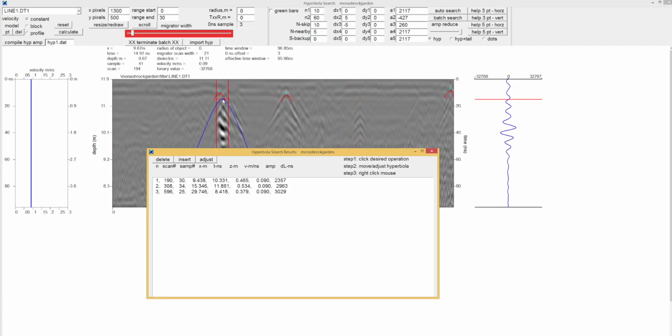And sometimes, as you can see, it gets it completely wrong. This is why this system is really only designed for use on concrete, where you're looking for reinforcing bars, or rebar, where 99% of the time in concrete there is no layering like this, and it's relatively homogeneous. You're only going to get the reflectors within the concrete block. You're not going to get all this other extra noise. Unfortunately, I don't have a good example of this, but that's how the system works.